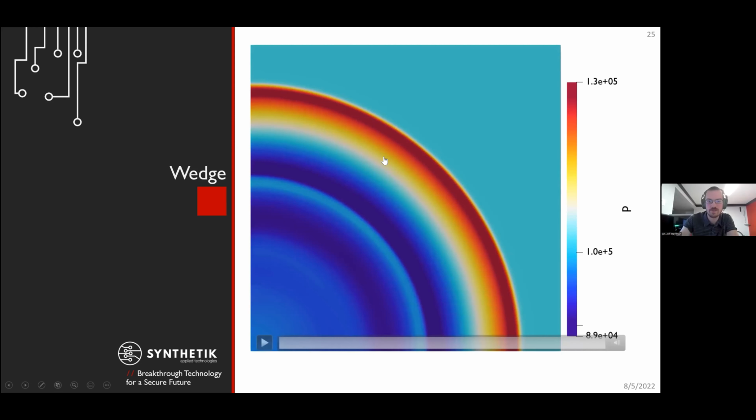So you can see we have our primary shock wave on the outside, and then you actually have a second one kind of in the middle, and then you can see a pretty low negative phase in front of that, as well as behind it, and then you get a smaller tertiary shock. So basically it just overexpands, collapses, and gets another detonation. And this is really due to that equation of state. And the bigger your charge, the bigger that effect.